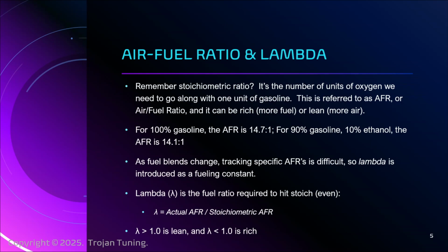And so this lambda becomes really important, because it puts every fueling conversation in an apples to apples comparison, right? And really forms the cornerstone in this world of transient fueling composition, of being able to effectively manage fuel and fueling and talk plainly across the board. So lambda, learn it, love it, use it. It's the accepted standard by tuners everywhere, right? I resisted lambda at first because it's a little tricky, but for years now I've adopted it, and I assure you it is the way to go.